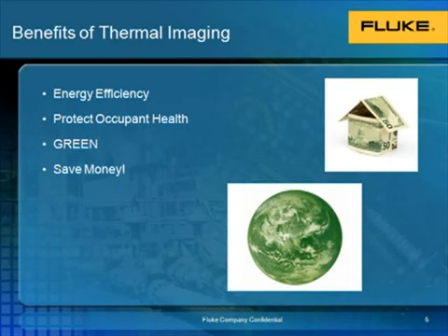As energy costs continue to rise, the efficiency of your home becomes more and more important. By utilizing a thermal imager, you can easily spot air gaps or missing insulation, for instance. The protection of the occupant health comes into play with mold, for instance. Thermal imaging is also a major contributor to the green movement. All this adds up to saved money.